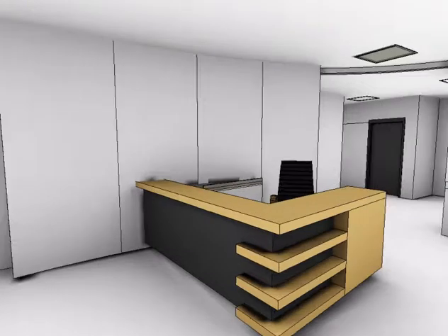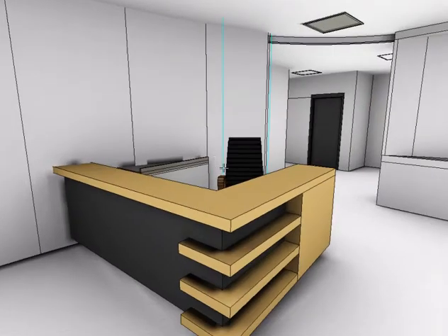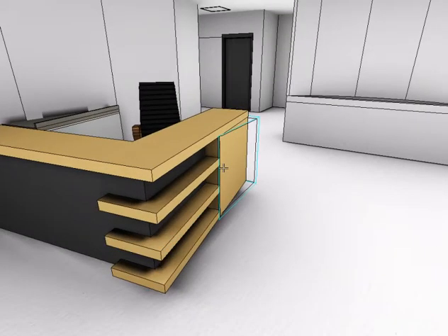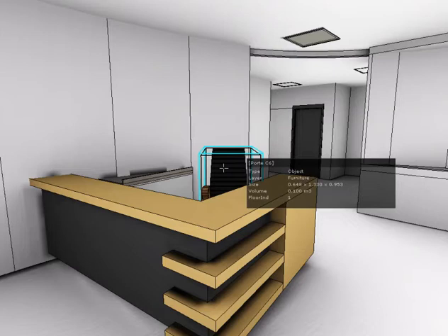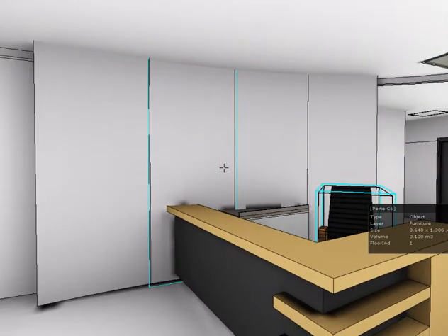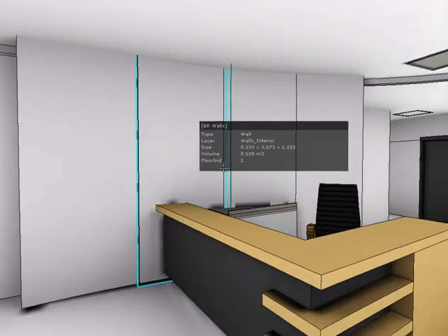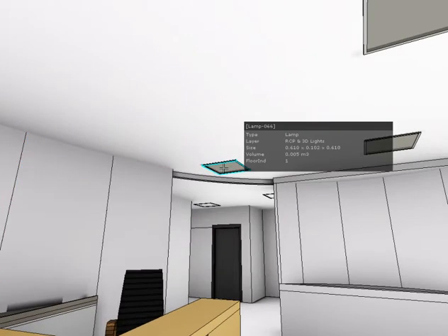Besides measurements, element information can also be displayed about any element of the project. Press the I key and notice that the cursor shape has changed again, and the element at the cursor has been pre-selected. The pre-selection changes as you move around with the mouse. Click the mouse at any time to display the element information palette. This palette will inform you of the element ID, type, and layer name, as well as the size and volume of the element and the floor on which it is located.